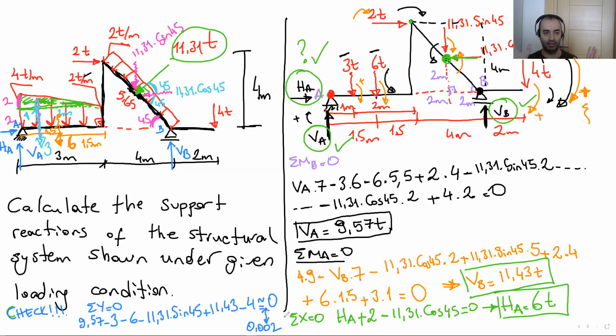The other part is easy. You have to consider the positive or negative direction. You are going to make an assumption at the beginning. You will assume one direction is positive. After that, you write all other moments according to that initial assumption.